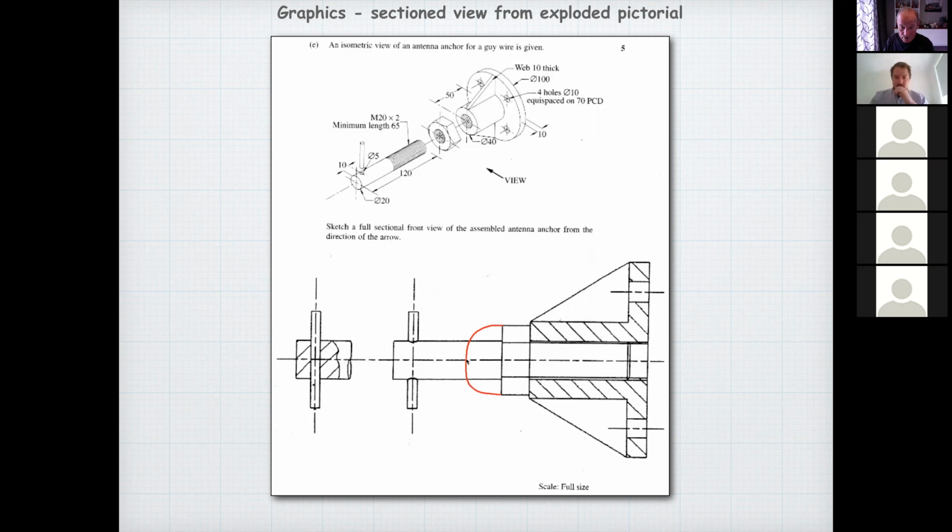And then using the radius, you mark there, you mark there. And so you've got your hexagon drawn, but it takes too long. See that line there? That will always go between the threads there. So don't waste time doing that. Just put it between the threads.